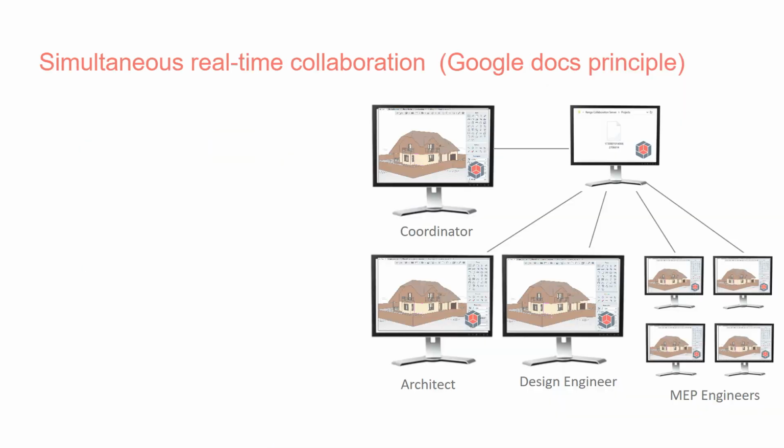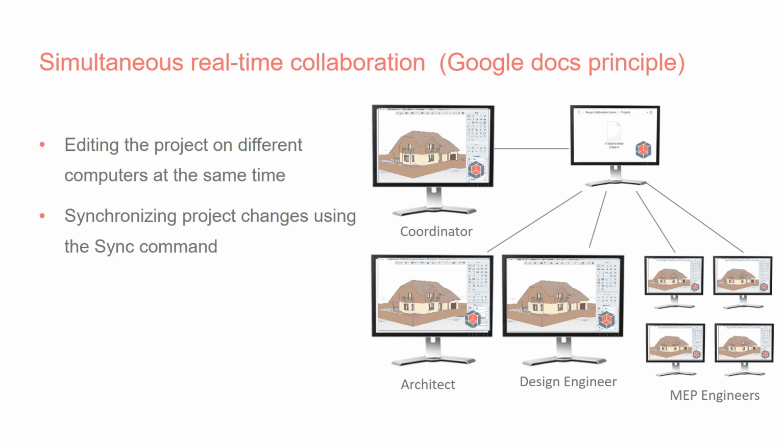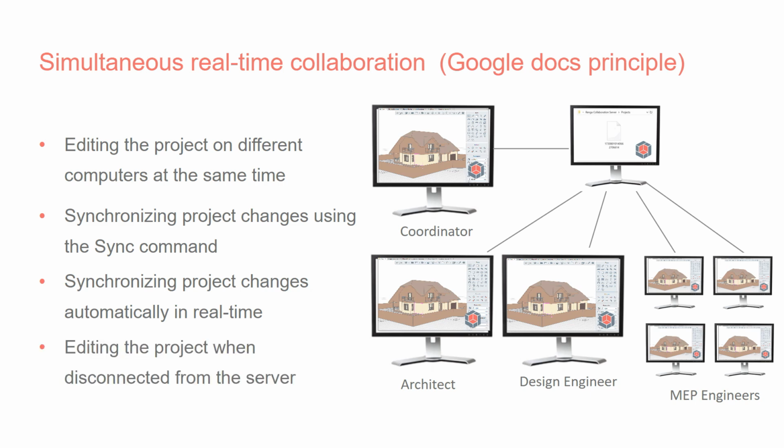With Renga, different users can collaborate on a project published on a collaboration server. Edit the project on different computers at the same time, with the automatic coordination of changes made by different users. Synchronize project changes using the sync command. Synchronize project changes automatically in real time. Edit the project when disconnected from the server, synchronizing changes when the connection is restored.